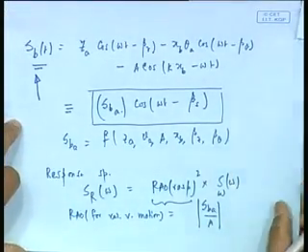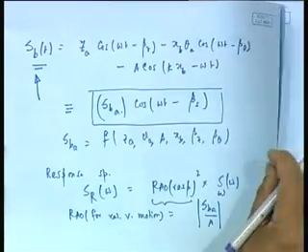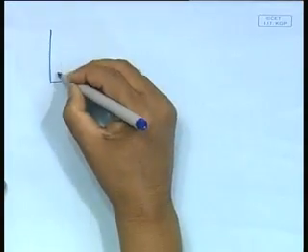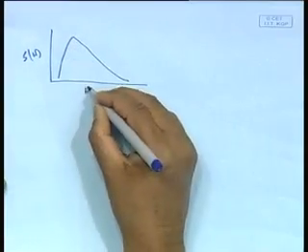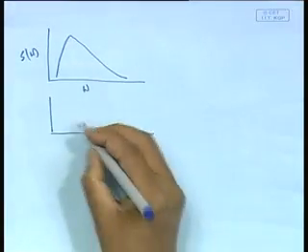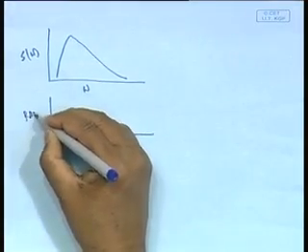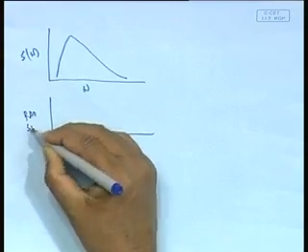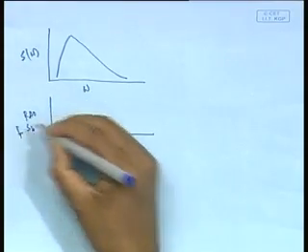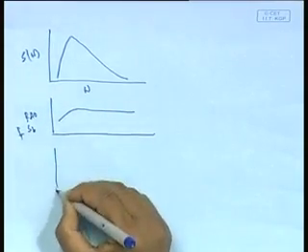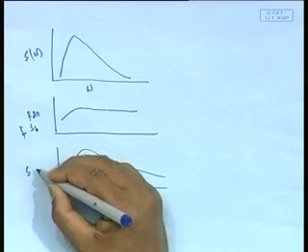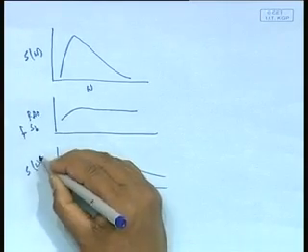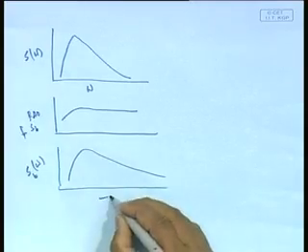So, once I can find the response spectrum, in this case I end up getting something like that. Again I get here the wave spectrum S(omega) versus omega. I get here my RAO for S_B, whatever that is, and then I get the spectrum S of omega of S_B versus omega.